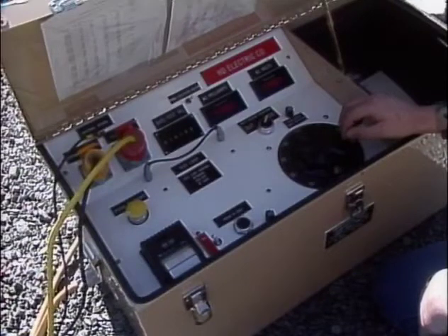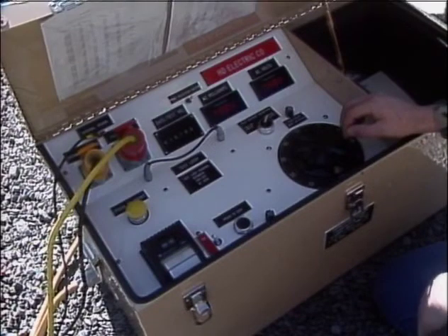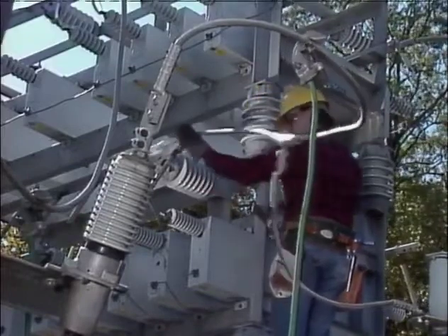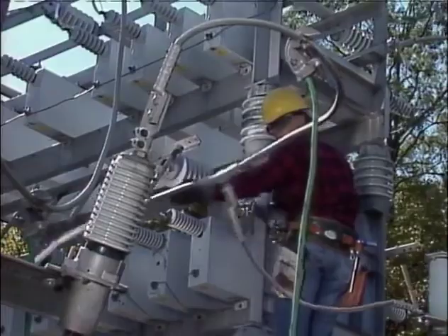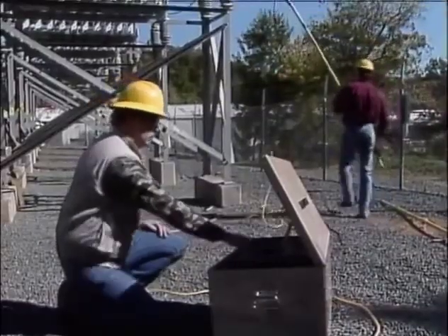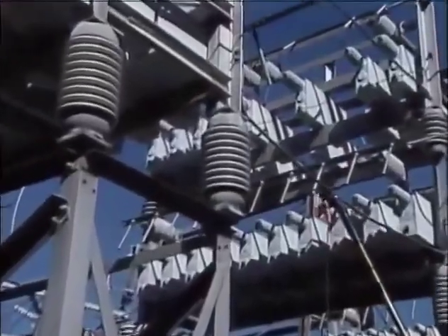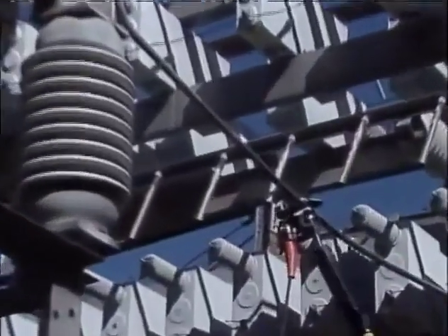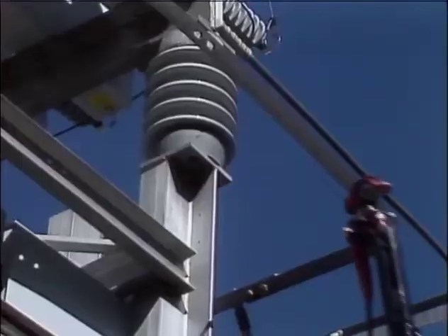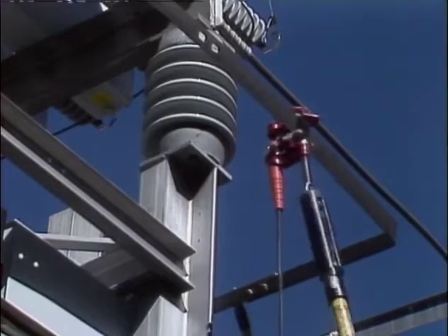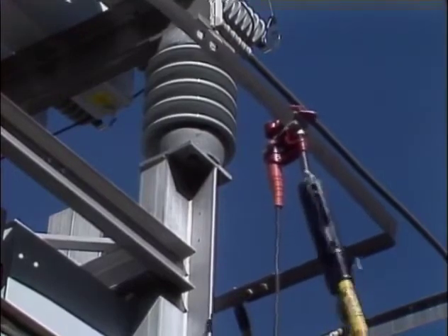With this approach, a test device is used to apply voltage to an entire section of capacitors. The capacitors are not disconnected from the bank. To perform the check, the grounded source conductor to the capacitor bank section is disconnected. One lead of the test device is connected to the neutral side of the bank. Here, the connection is made to a conductor that connects the neutral frames of the bank. The other lead is connected to the normally hot side of the bank. Here, the connection is made to the normally hot bus of the bank.